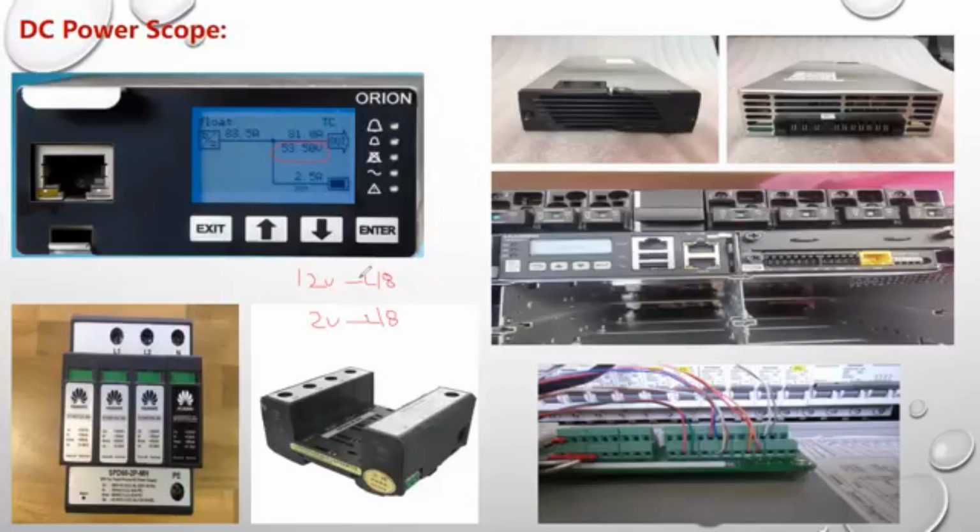I'll tell you simply, the battery of 12 volts in case of full charging isn't actually 12 volts. 12 volts can actually be, let's say, for example, 13.10 or 13.3. So it can be 13.3 or 13.10. And this is the case of full charging. And the same goes for the 2 volts. It can be 2.41 in case of full charge.